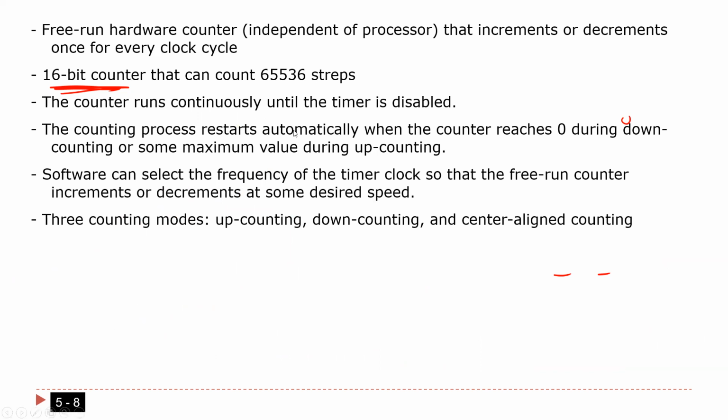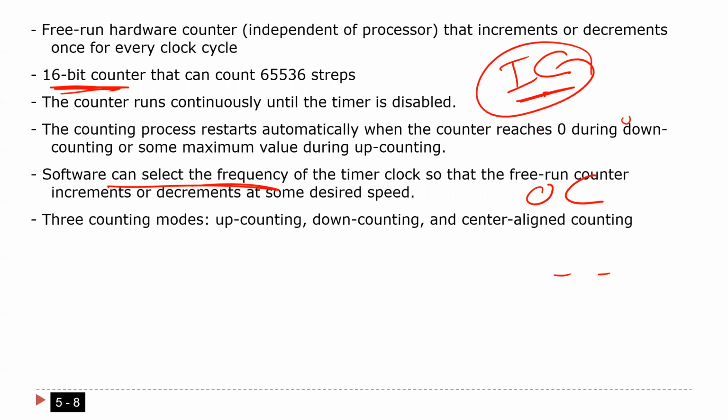The counter restarts automatically when it reaches 0. I'm going to explain what I mean here. In software you can do initialization of this counter. Wait a second. What I'm saying is that we have a counter, and I'm going to explain the relation. You have just told us you want to do input capture and output compare. Input capture means you want to measure time, and now you are talking about a counter. What is the relation? For sure, there is a relation, and that's what I'm going to explain.